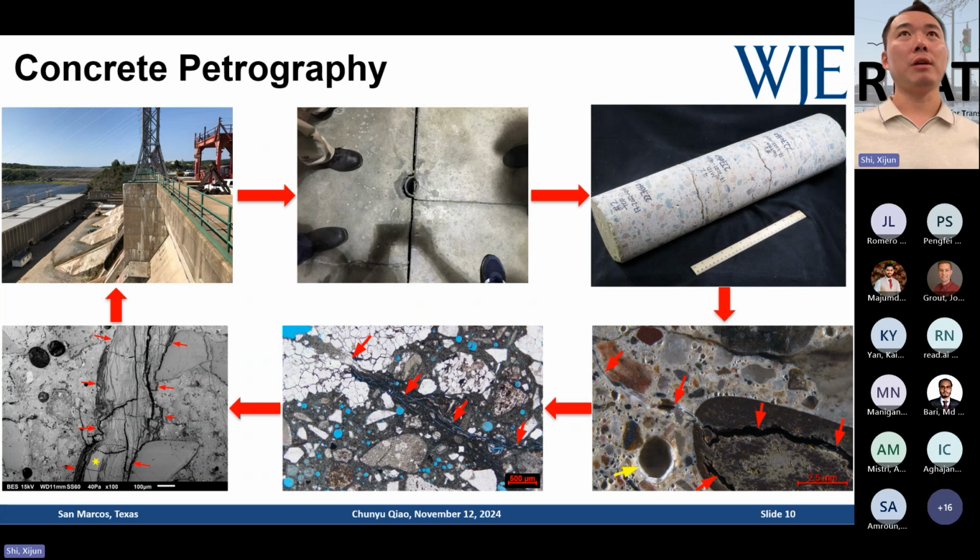Engineers try to say, okay, let's give some saw cuts to some slabs or some members to release the stress. You can see a hemispherical-like hole over there, but that's back from 40 years ago. That was a circular, a concrete cylindrical core. After 4 decades, of 40 years, of continued cutting, you can see how much expansion has occurred and how much expansion they tried to eliminate in that structure. It was a core hole that was spherical; right now, it's half spherical. So that's the on-site inspection and some routine inspection.